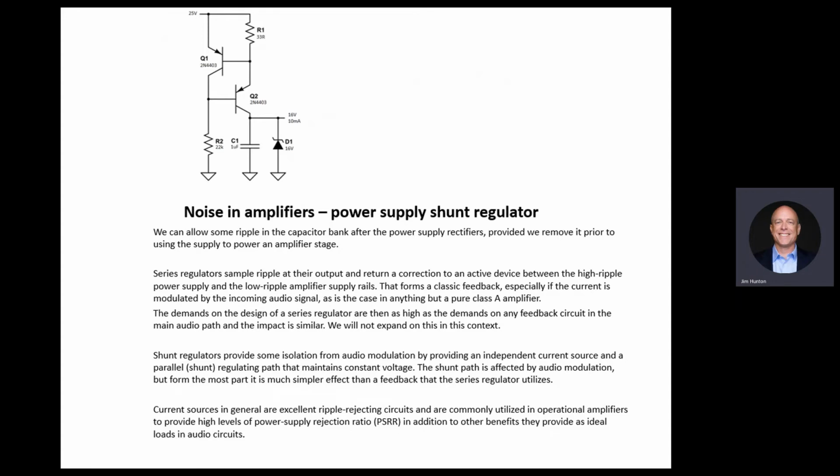This Zener will conduct all the time, 20 milliamp. And if your circuit decides to consume 5 milliamp less, it's going to go into the Zener. In a sense, this circuit fixes, by being a current source, into a voltage stabilizer. It fixes the voltage on the output with no feedback. There is some AC effect when you're modulating the current on the output, but much lower than a series regulator, which everybody's doing.